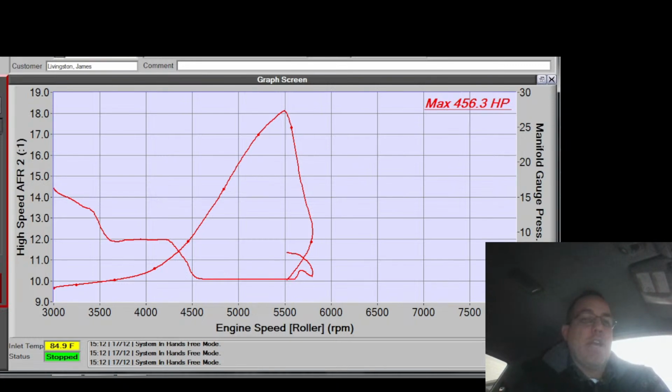They work good at one specific boost pressure. You tune them for that boost pressure and they work better. I see. Just not enough resolution or control. Yeah, it's just so finite. Well, the diaphragm's really small compared to the piston size, so it has not very much leverage. Yeah. Less authority. That's what I was thinking. Yep. No authority.